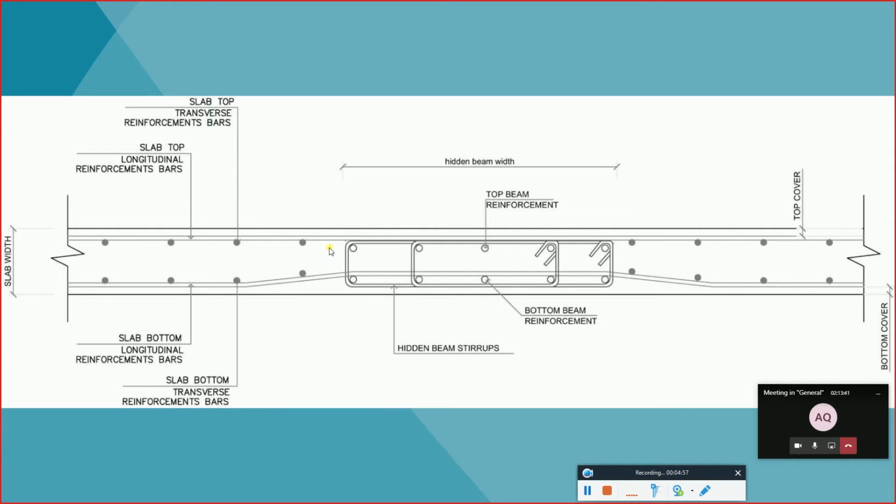So if you remember the basic equation of the deflection, it is related to the I value. Deflection is proportional to the moment divided by EI. So if we increase the I value, that is bd cubed over 12, it means that the member is going to have more moment of inertia, more I value. If it has more I value, deflection is going to be lesser. Once again, deflection is related to bending moment divided by EI. If I increase the I value, my deflection is going to reduce.